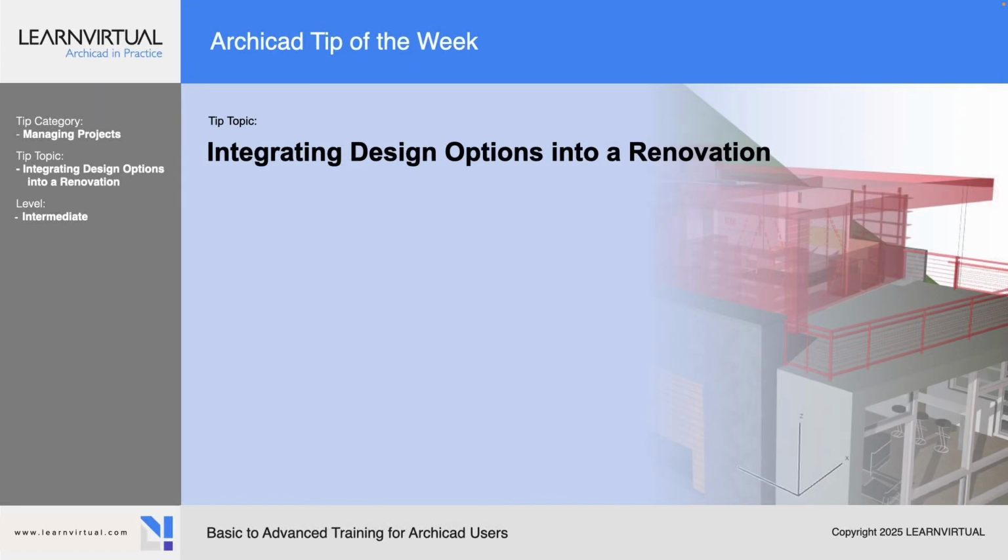So when we want to create a renovation view, once we've set all this, we want to save that view so that it contains all the information for that particular renovation setting. So for example, whenever we go to save a view, we can actually set the renovation filter. Again, we can select the demolition plan, we can select new construction, we can set existing plan, etc. And then once you've set that, it's going to contain the information for how you want that particular renovation view to look.